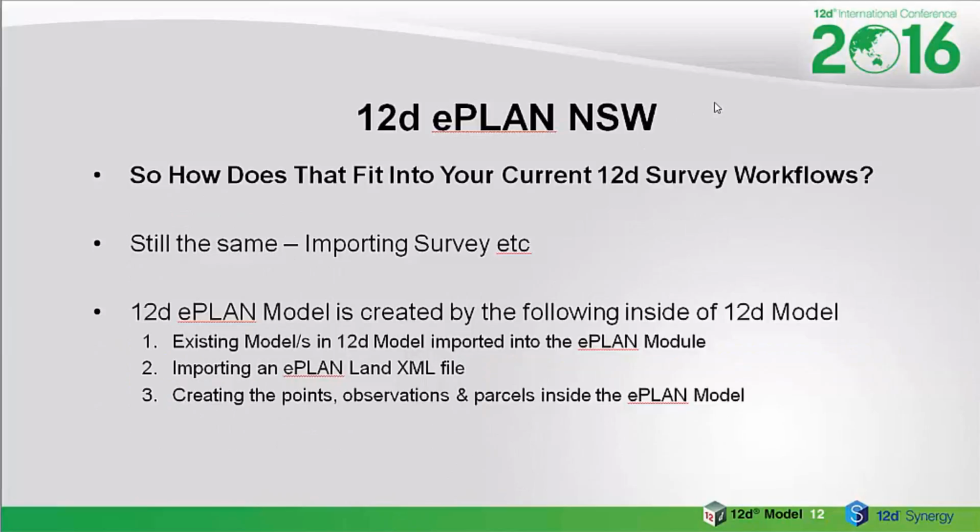Alright, so how does ePlan fit into your current 12d survey workflows? You can still go about and use your same methods. Now you've got to remember that ePlan is purely just for creating these LandXML files that get sent to the LPI. It's not something you'd give to your client. So if your client still wants a drafted linen plan, then you still have to use CAD and create these plans and then plot them out and give them to your client.